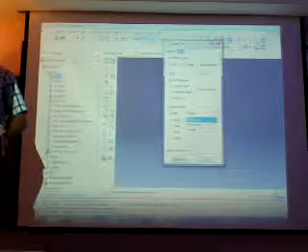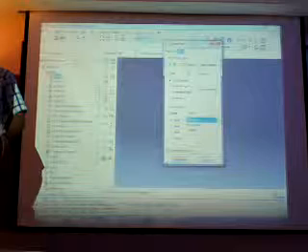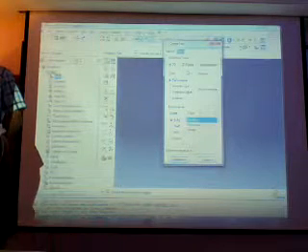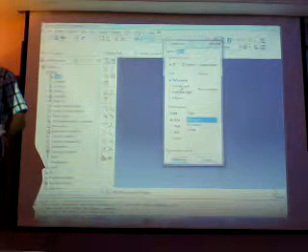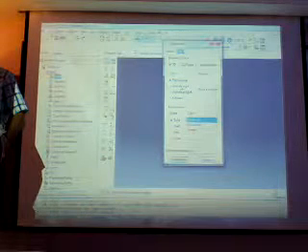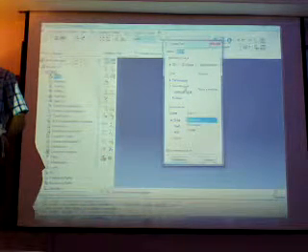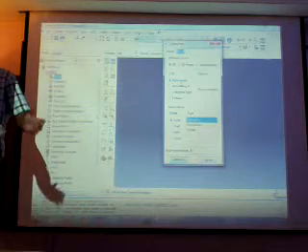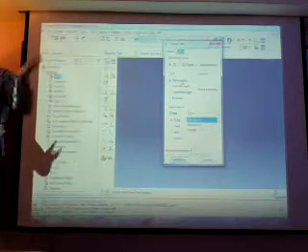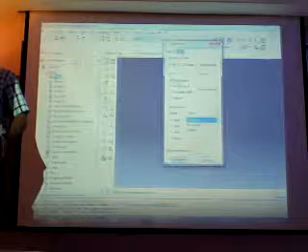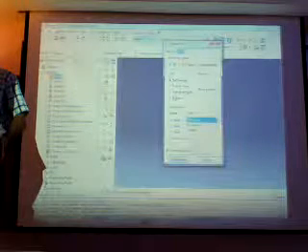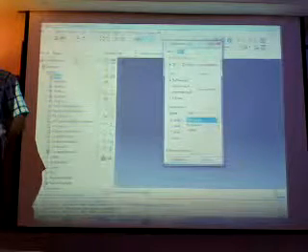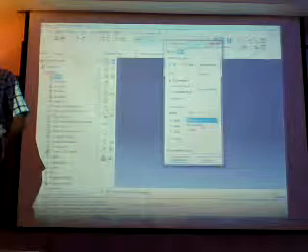For example, in forging or deep drawing, for the die or punch, we take discrete rigid because we assume we don't have any displacement and deformation in the die. But for the part, we need to define deformable. Or for example, you want to simulate a bar, we need to take a deformable part. And we have different types of feature creation.